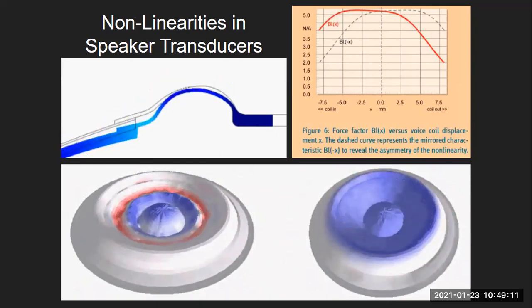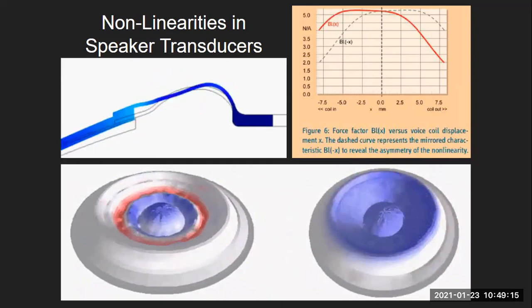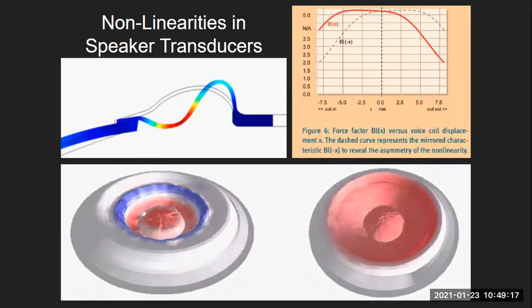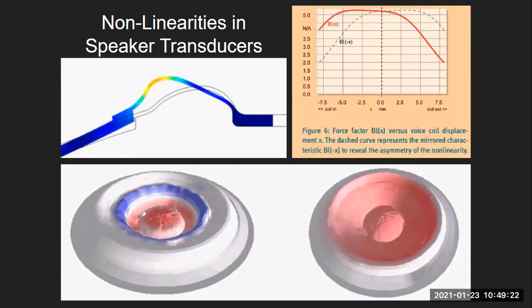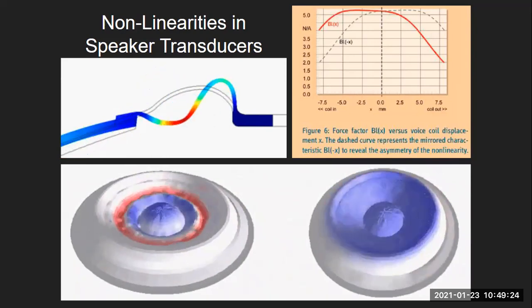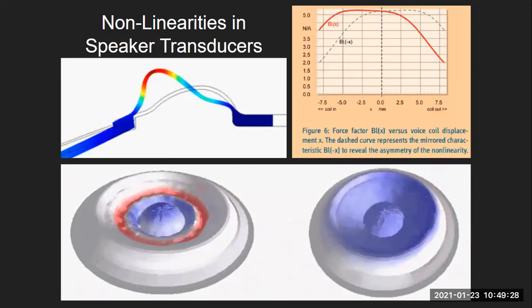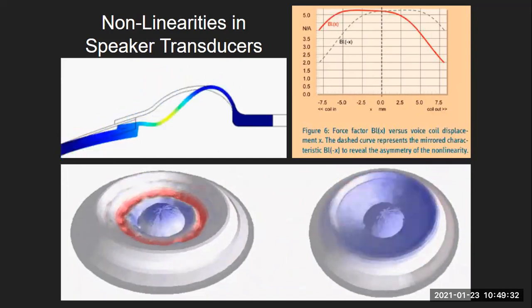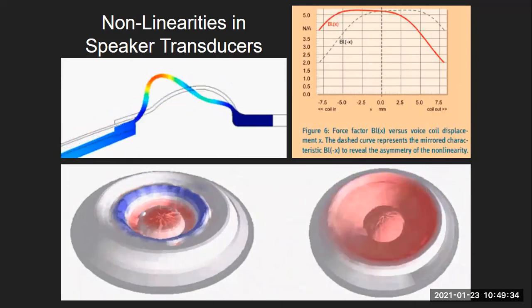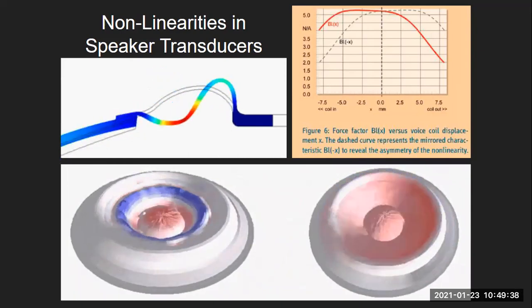That's something we call power compression, and that's a big deal for people who work with large format sound, when people are really trying to pump concert level audio. They care about power distortion because you're typically running at the limits of the speaker. And if you don't have linear magnetic force, then you end up with quite a lot of distortion.